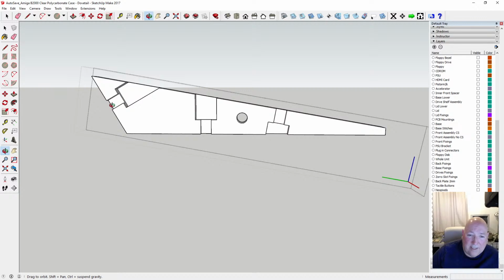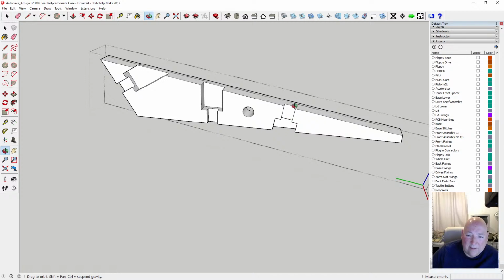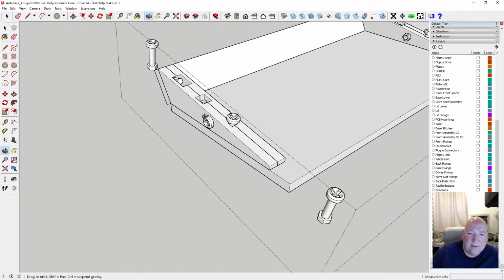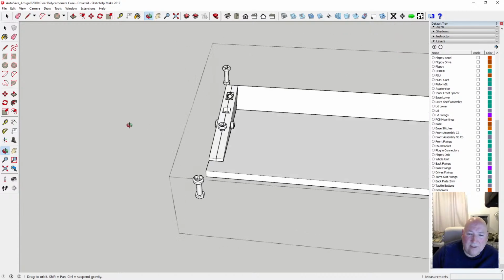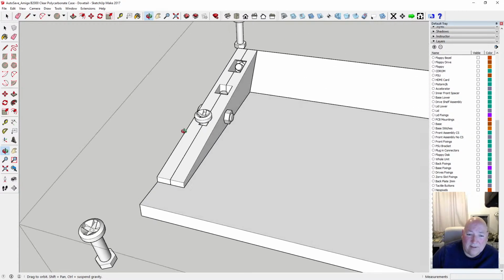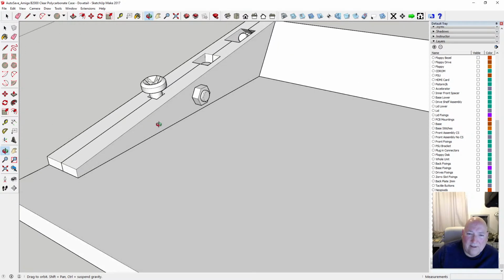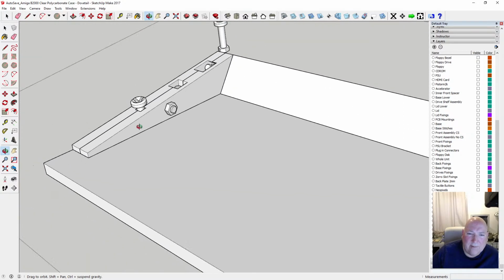The nut goes in there, and it did a good job, but it just split. Where I've milled it, I've made it thinner, so if we put stress on it, if we over tighten it, they'll crack. But if I glued them 2 together, like that, just glue them, they'll stay with super glue, but they look horrible. Acrylic cement, maybe, that'll do the trick. Expensive stuff though, acrylic cement.